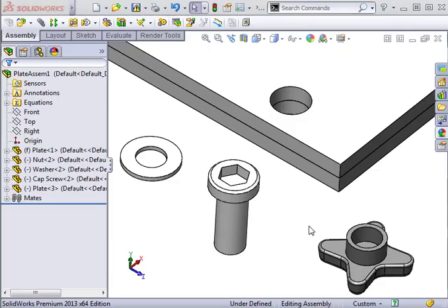When building assemblies that require lots of mates, it can sometimes be an intensive process. Fortunately, SolidWorks has an option called Multiple Mate Mode. Multiple Mate Mode basically allows you to mate several entities to one reference entity. This can be a huge time saver in situations such as mating hardware stack-ups with their corresponding holes or many